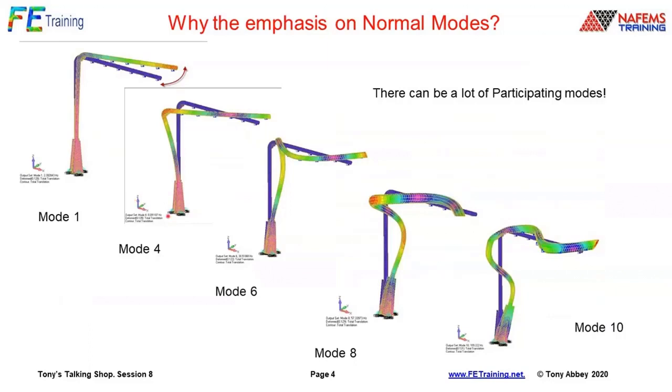If I hit that laterally, then subsets of the modes can get excited. On the course, with this gantry, we do a seismic analysis, and then it's really just the first mode that gets interesting. Then we put it on the old shuttle cargo bay and do a random response analysis and actually launch it into space. We go up to about 2000 hertz, so the higher modes then play a role. So these contributing modes and understanding them are very, very important.